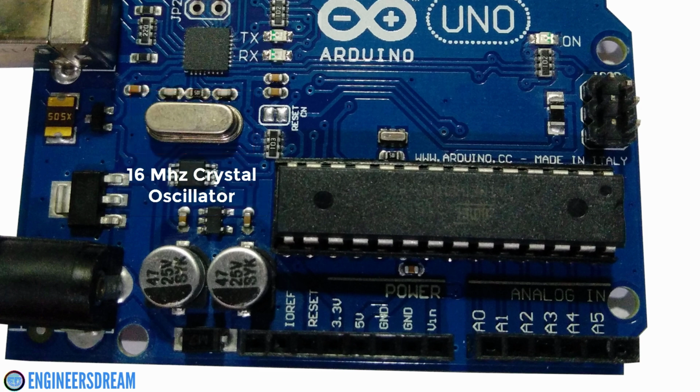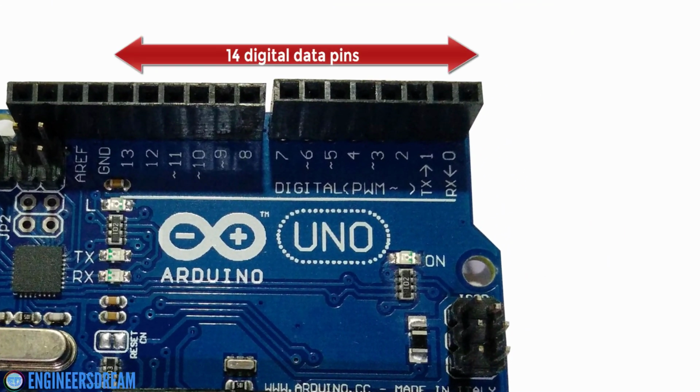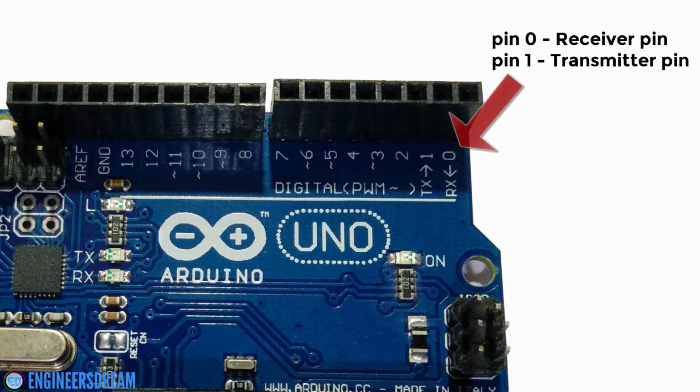And as I told you earlier, the Arduino board consists of 14 digital pins which are labeled from 0 to 13. If we look at pin number 0 and 1, then over here RX and TX is written, which stands for receiver and transmitter. So we can basically use pin number 0 and 1 for serial communication, that is for communication between a Bluetooth, GSM or even your computer.